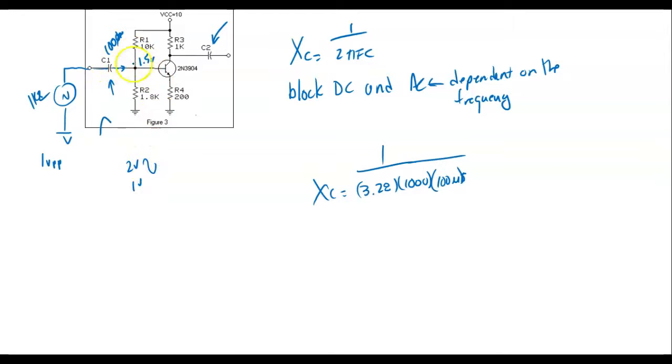The temperature is not changing this voltage; the input signal is changing that voltage. So what does that capacitor do? It allows us to bring AC into a DC circuit without affecting either one, without creating a short circuit. Now, this is not AC right there, that's DC. This thing's got a gain of 5, so if I'm putting 1 volt peak to peak in, it's going to go up to 5 volts peak to peak out, right?